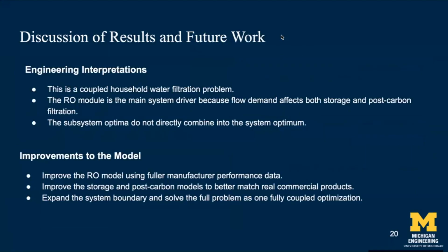Finally, this project is ultimately a coupled household water filtration problem. The RO module is the main system driver because flow demand affects both the storage unit and the post-carbon filter. In future work, the RO model can be improved with manufacturer performance data, and the storage and post-carbon models can be made more realistic by matching commercial products more directly. And the full system can be solved as one fully coupled optimization problem.